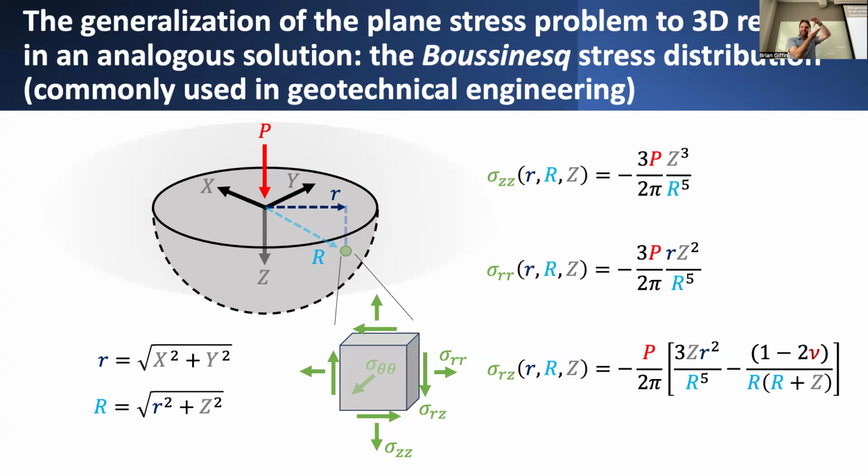So the more pressure you have on some piece of granular material like a soil, the more shear load it can sustain. And we'll examine exactly how that manifests as a three-dimensional failure criterion on the stress in chapter 4. All right, just to give you some perspective on that and how it relates back to geotechnical engineering and other interesting applications of this theory.